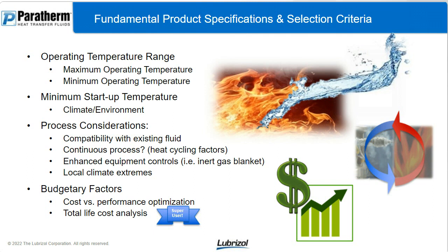So total life cycle analysis, top-off rates that you're going to have to do, testing you're going to have to do, change-outs. If you're going to have to dispose of the fluid, that's going to be a cost down the road. So take that total life cycle cost analysis into play when you're specifying a fluid itself.